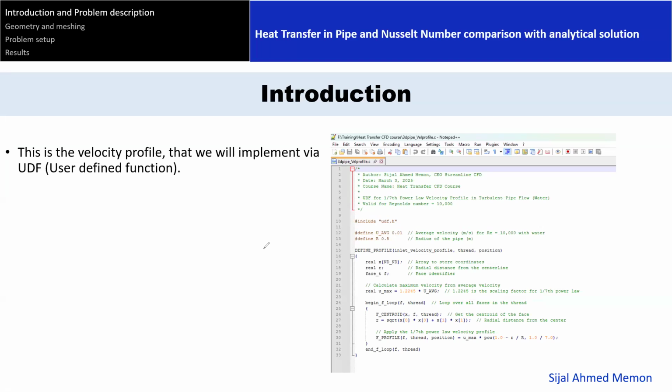When we talk about the mean velocity, or any length or any velocity, those are actually the reference conditions. Length would be the characteristic length, the length that is going to define the character of the flow. For example, in case of an aerofoil, the characteristic length will be the chord length. In case of a tapered wing, the characteristic length would be the mean aerodynamic chord. For pipe flow, it would be the diameter. For a vehicle body, its height would be the characteristic length.